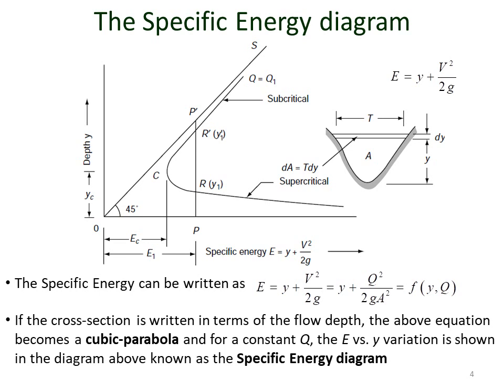The E versus Y variation, or the specific energy versus depth variation, is shown in the diagram. Remember that this is the shape of a cubic parabola, and this is known as the very famous specific energy diagram.